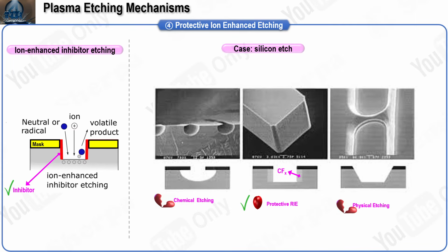For silicon, the typical feeds are fluorocarbons such as C2F6, C4F8, and CHF3. They generate CF2-like fragments that build the protective polymer while fluorine-bearing species provide the etch chemistry that turns silicon into a volatile product. A small oxygen addition is tuned to balance polymer and etch. Too little polymer gives rounding and the profile drifts isotropic, too much oxygen overpassivates the surface and slows the cut, and oxygen also attacks photoresist quickly, which is why strong passivation recipes often use a hard mask.